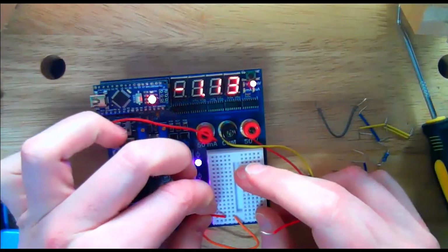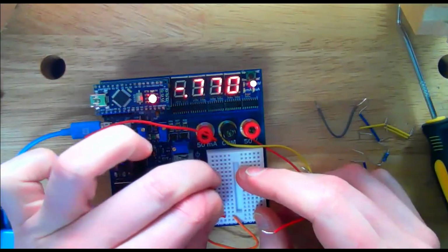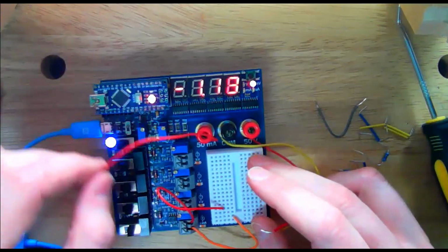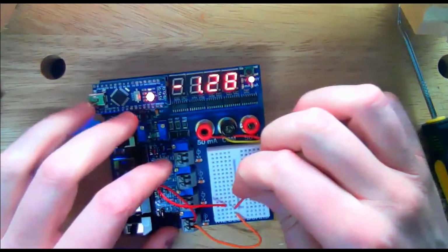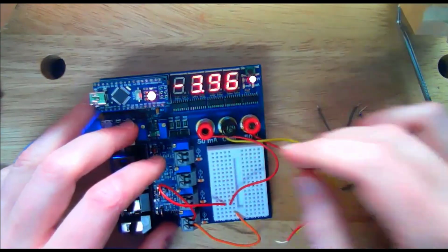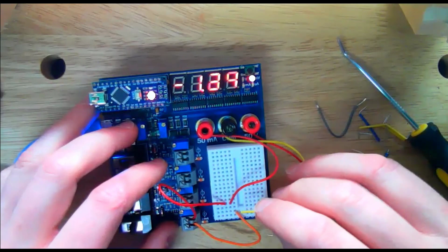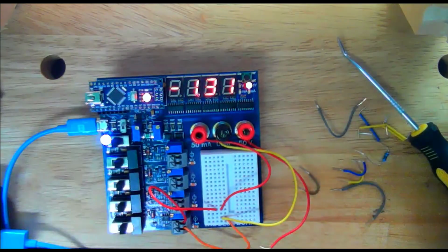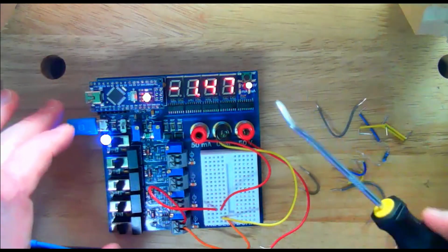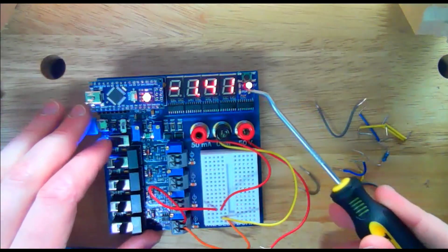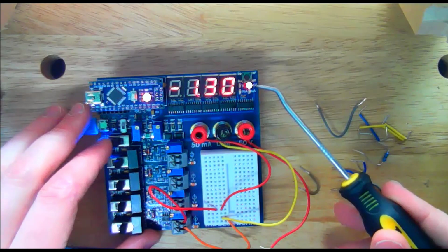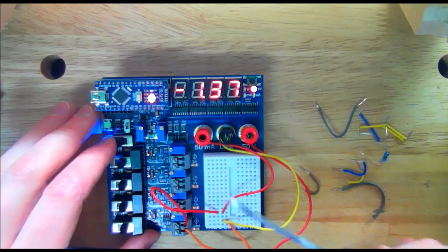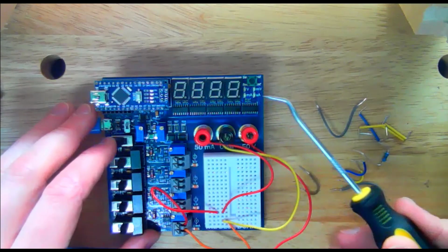Anytime you want to measure current, you first of all de-energize. You break the circuit. I always break the circuit by connecting it to a different row. Then we're going to have the top row flow into the current meter, and the common terminal of the current meter connect to the bottom side of the current supply. Notice right now we have volts and millivolts; millivolts is illuminated. When I energize this board, the board should detect that there's now a current being measured, and it should switch to milliamps or microamps.